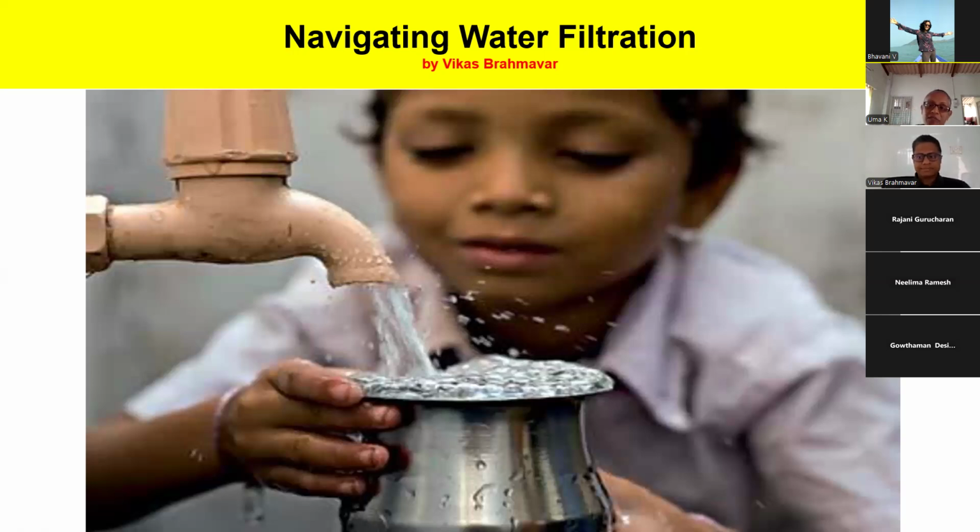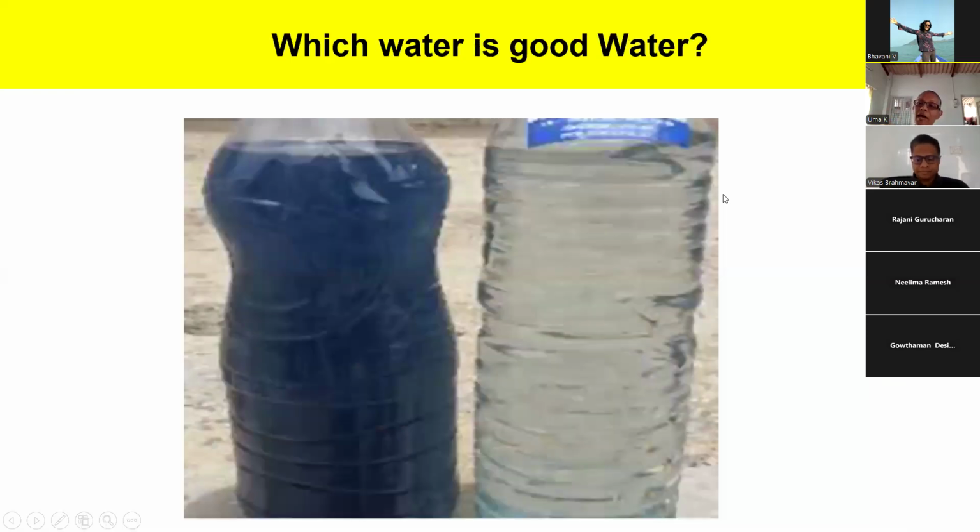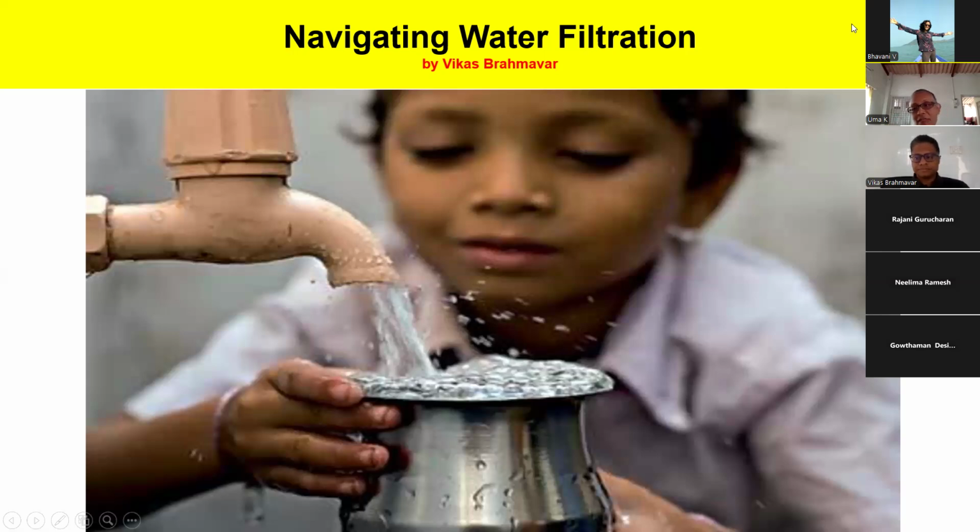Another area, related to this, is how treating and reusing wastewater can be a climate mitigation strategy. That is being helped by the Karnataka government's project, wherein they are pumping the treated sewage from Bangalore into several lakes in the hinterland. The purpose is to recharge the groundwater. What we have seen is that when the groundwater is recharged in these lakes, the surrounding wells and borewells, which had dried up, especially in drought hit areas, become active and start holding water throughout the year, because the treated wastewater goes out every day.